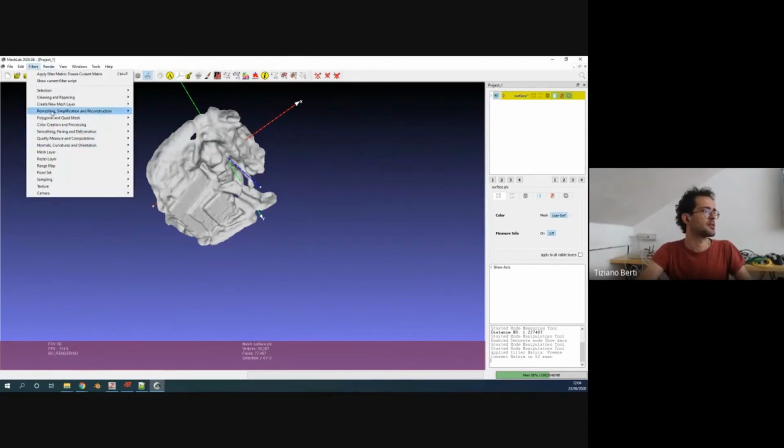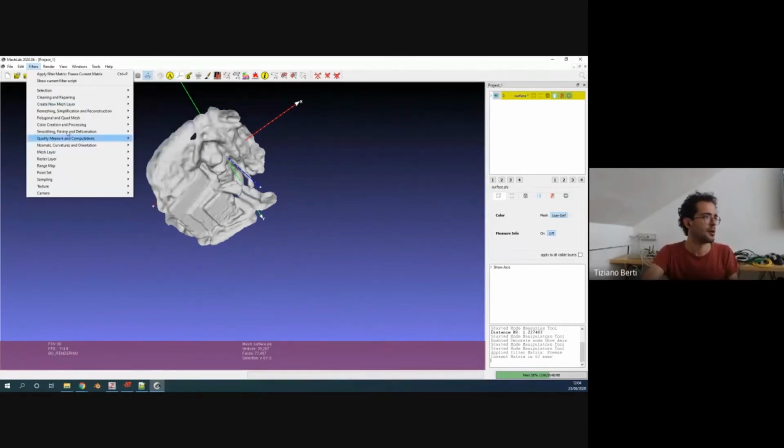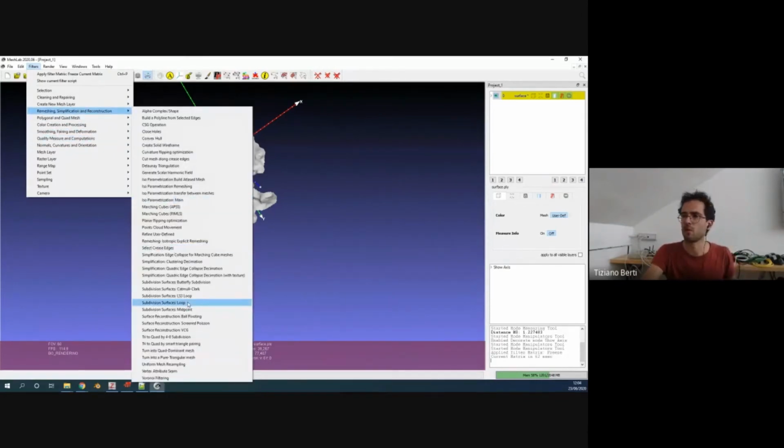The only thing I'm saying is, if you need to work on point clouds, which is what we were talking about before, so you got a scan of a building, you got a bunch of huge point clouds, you can use this software to align them, make a noise removal algorithm, remove points that have a bad quality compared to others, and make a lot of filtering. There is a huge amount of really good mathematics inside this software.